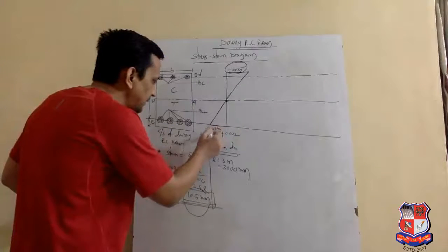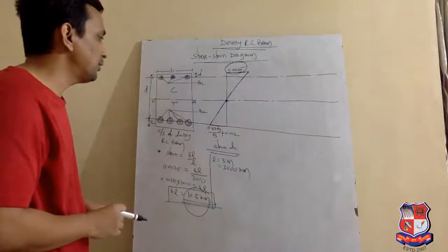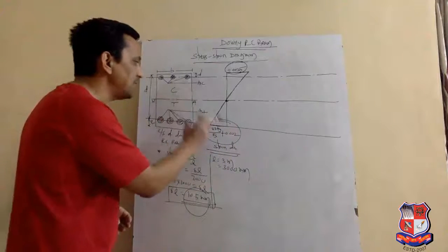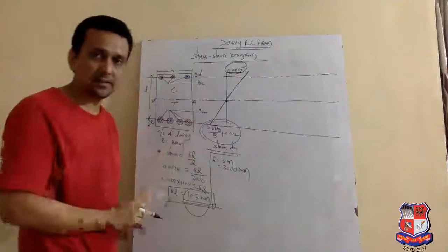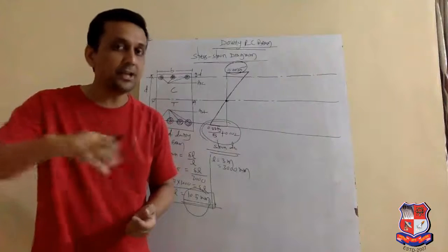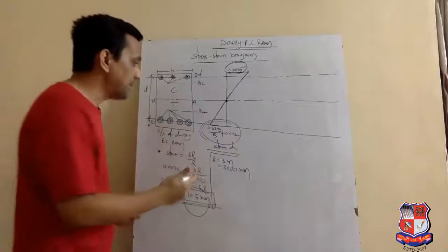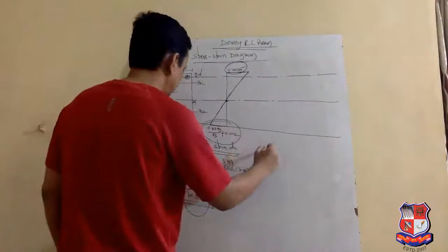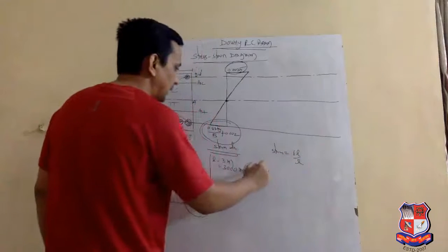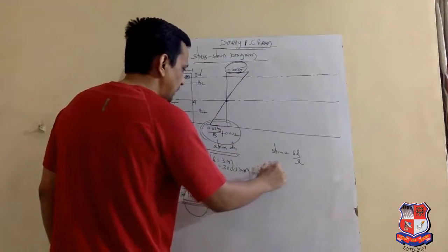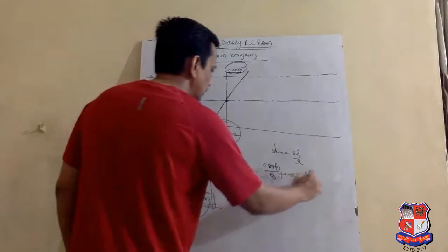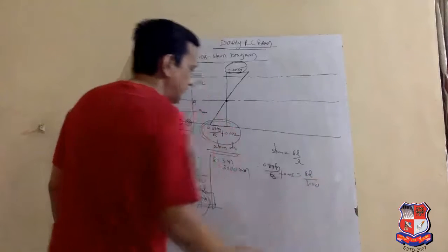And 0.87 Fy upon Es plus 0.002. What is this value? This is the value of maximum tensile strain in steel. Again, it is difficult to visualize the failure in terms of strain. Let me simplify this in the form of deformation. We know strain is equal to delta L by L. The maximum strain is 0.87 Fy upon Es plus 0.002, and consider the length of the beam is 3000.